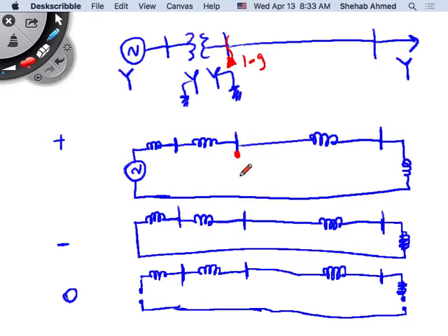Because you will still end up with the negative sequence and zero sequence not having currents, right? But we know that if it's a single line to ground fault, do I expect to see zero sequence current or not? Well, from the discussions we had, I said that anytime you have something connected to the ground, meaning current flowing from the neutral to the ground. How can it be connected to the ground? It will be if there's a single line to ground fault here.